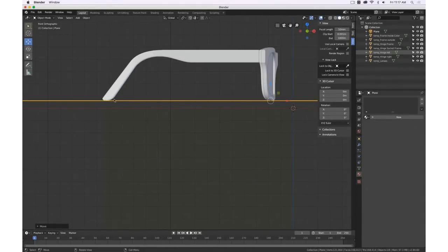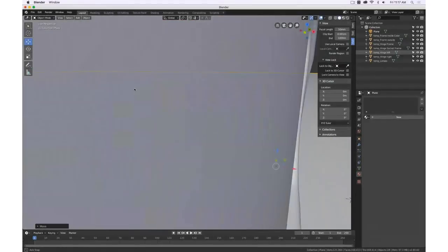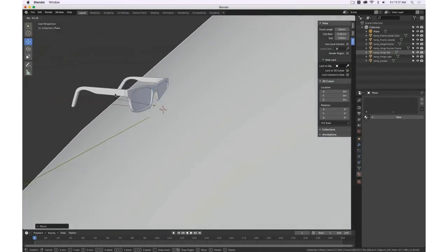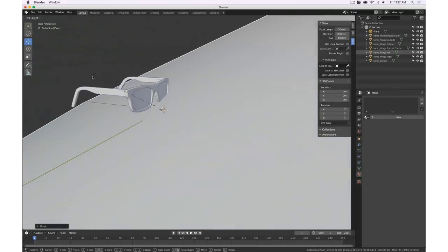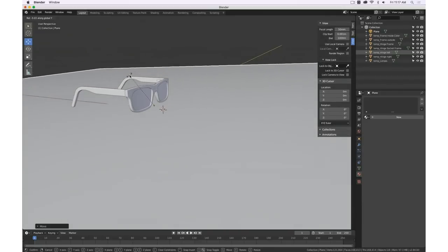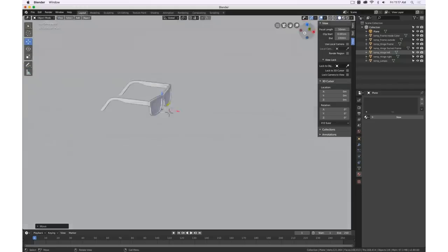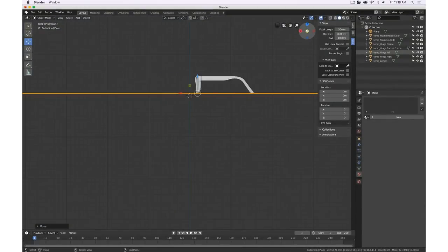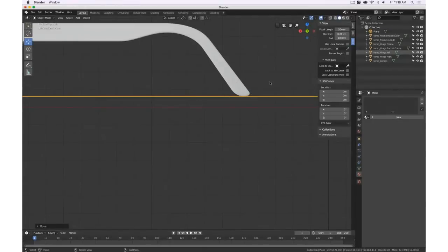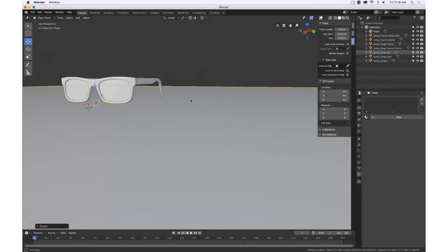And you see I'm in a side view. So R, and then I rotate this along the y-axis. If we are a little bit like in the 3D view, when I press R, you see the rotation happens along the view. So I can press Y to restrict the rotation only along the y-axis. But this is sometimes a little bit more confusing or complicated to do, which is why very often when I do these manipulations, I always switch to the individual views. And then I can just press R till it fits. Very good. Okay, nice.